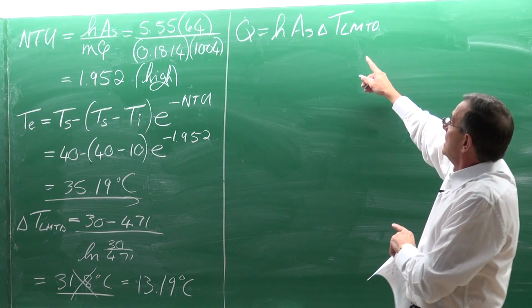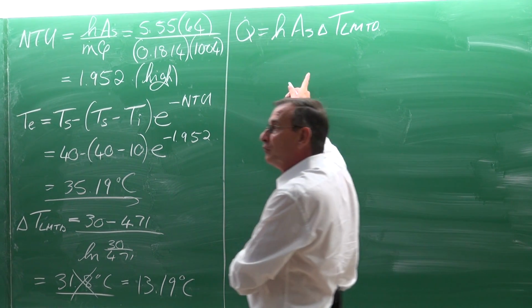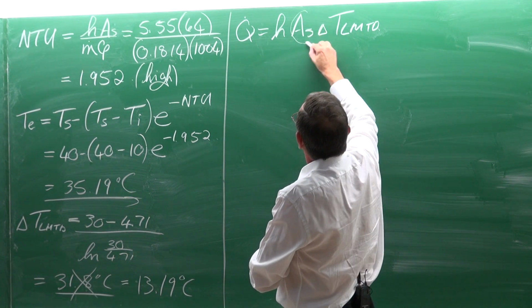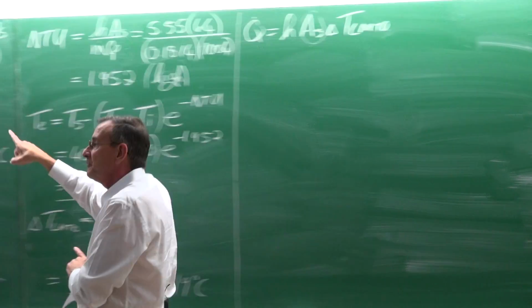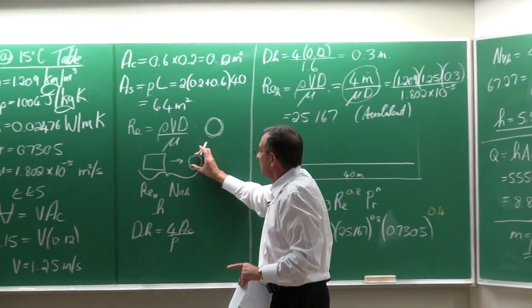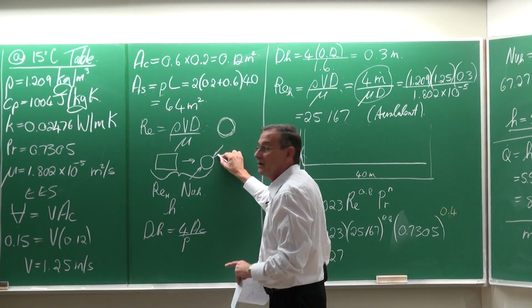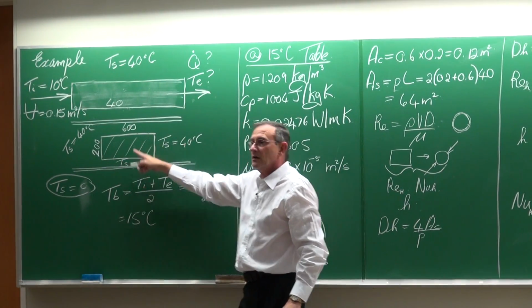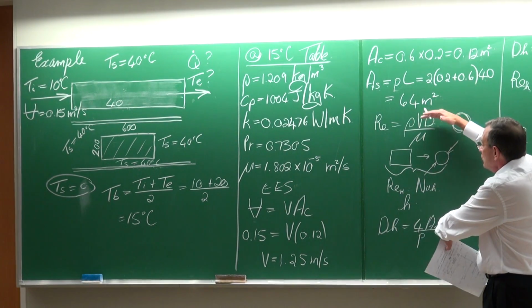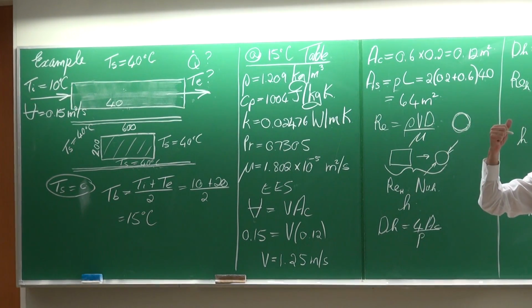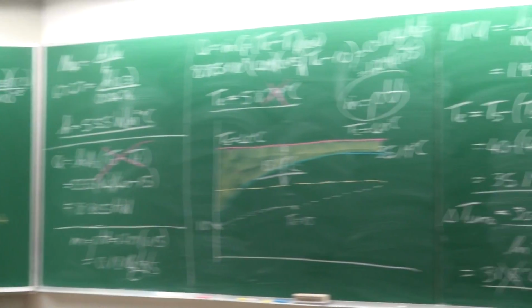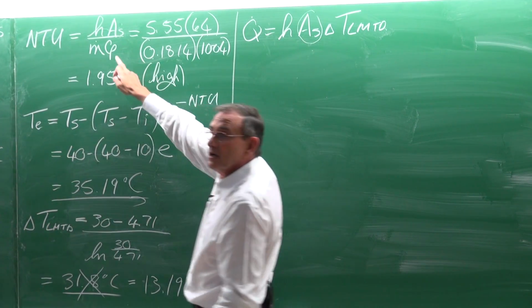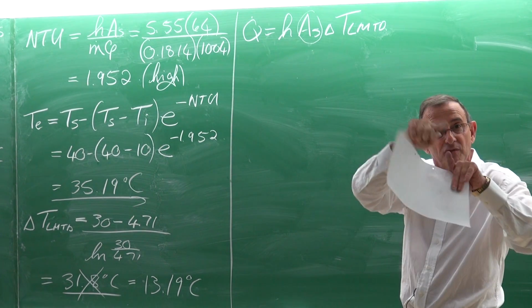Okay. Again, remember, do not get confused, because now students look at this and they use the surface area of this duct of 300 millimeters. It shouldn't be this surface area, it should be this surface area. Why? Because we only use this approach to get the Nusselt number, to estimate the heat transfer coefficient. That's why we do it. But for the rest, you always work with the actual values. Here also, the surface area was not that of a circular tube, it was of the duct itself.